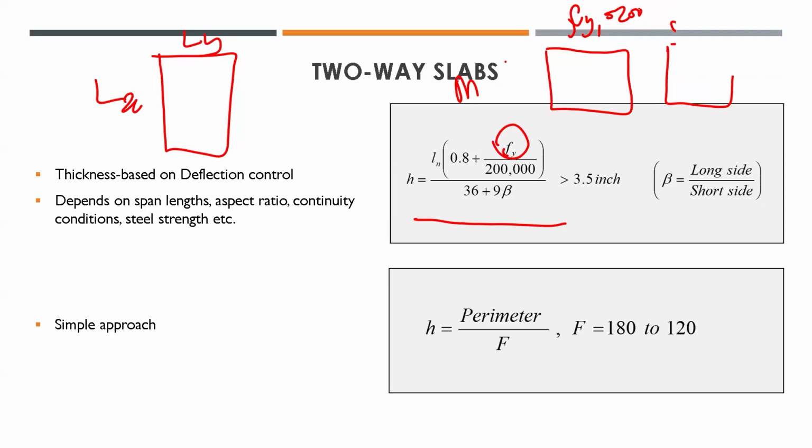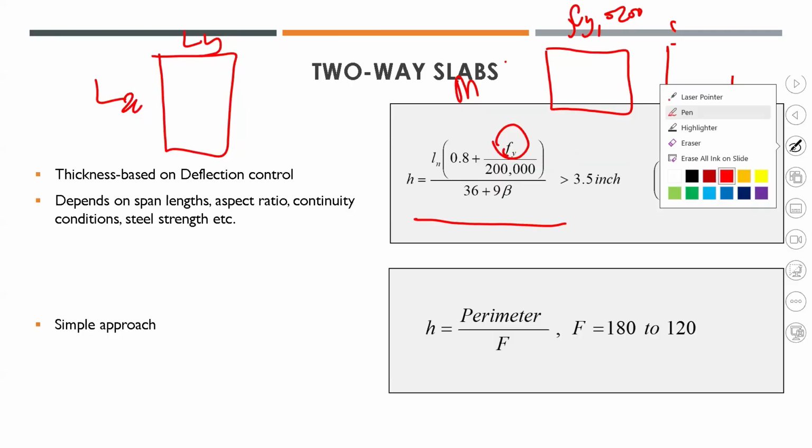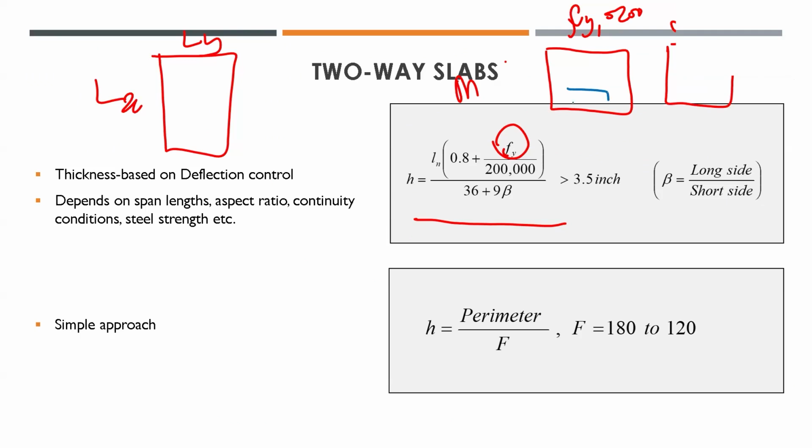More reinforcement, right? Because low strength steel, in the calculation, it should give me more. So I will get more AST here. So I will get area of steel more here, correct? For the same moment, for the same thickness, I will get a smaller reinforcement here, correct?